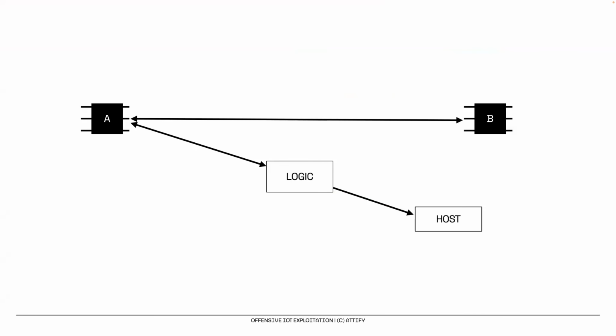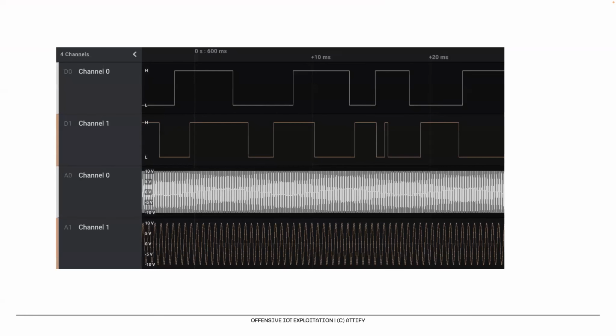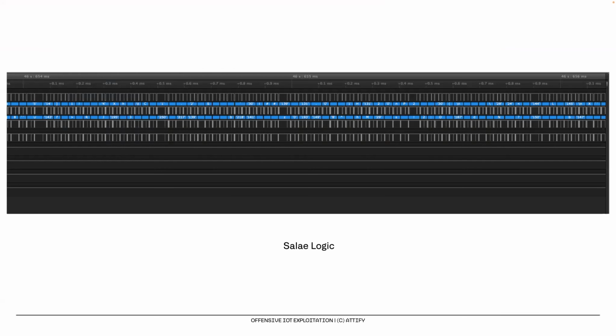You can use this tool called Logic Sniffer and capture the communication between two different chips. This will also give you more insights about the internal packet structure of the particular protocol and how the chip is communicating. That will also help you gain more understanding of how the device functions. It can also help you recover keys, especially if it's a very unknown protocol that you're working with, but you know that this is where the key is stored. So you just want to sniff that particular key as soon as it's transmitted from that chip, and then you'll have it in the logic view.